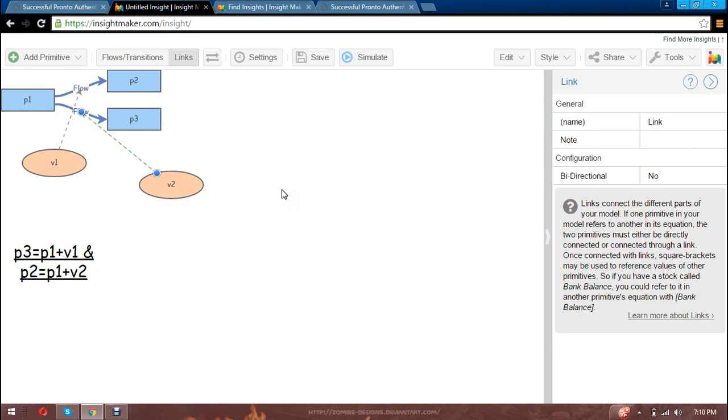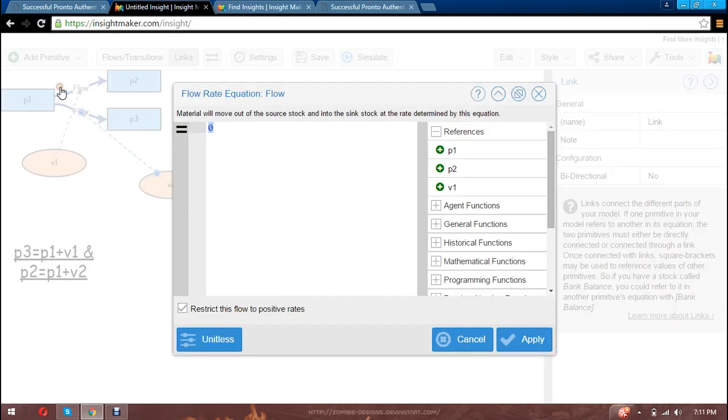And now we are going to do the calculation part. For the calculation, we can move the cursor to P1 here, and you will find the arrow mark like this, and you will find two blocks and one variable here. Here we are going to do the following operation: we are going to add V1 and P1 for the calculation of P2, right? Just click on P1 here and V1 here.